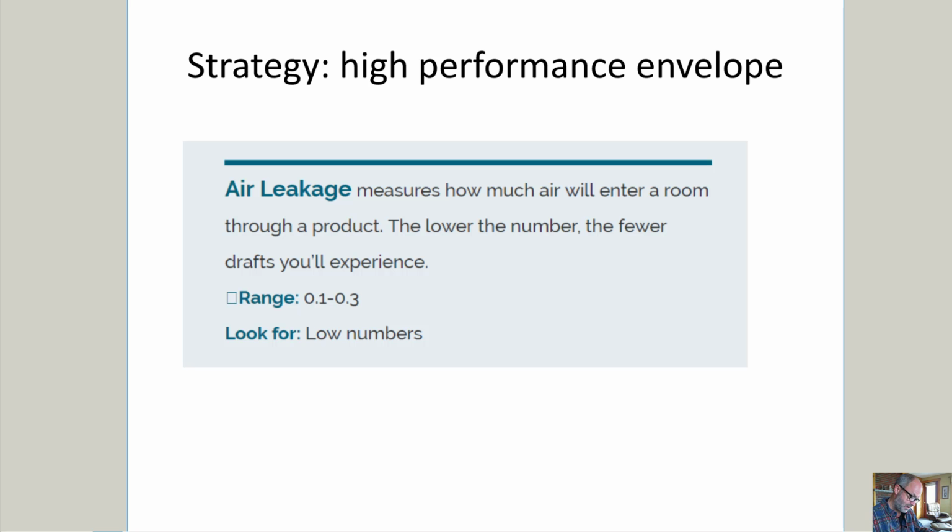And finally, air leakage. All windows leak a certain amount, some worse than others. You think of the old houses we live in. There's a lot of air coming through the gaps around those old double panes. So you're looking for lower air leakage. Air leakage is bad. It takes heat out of the building at a pretty astonishing rate. I've seen numbers as high as 30% of our heat is just air leakage from the standard building.